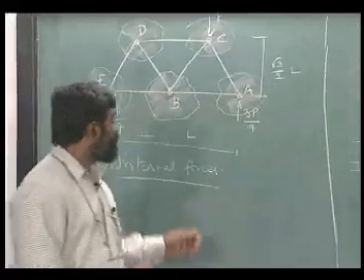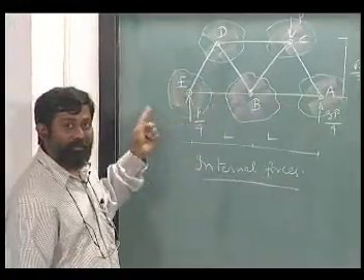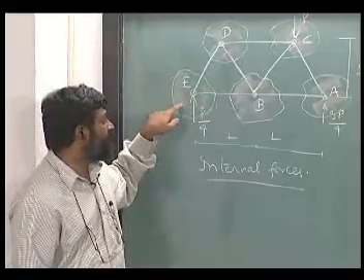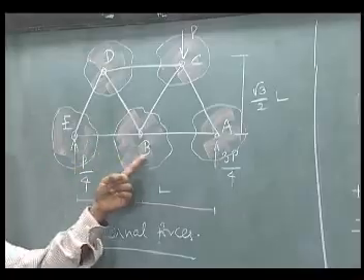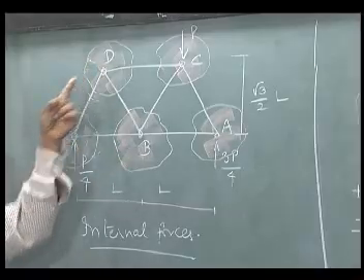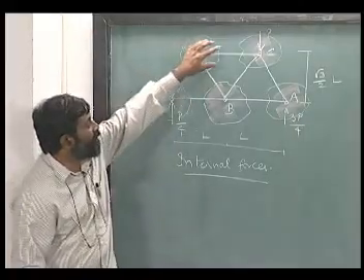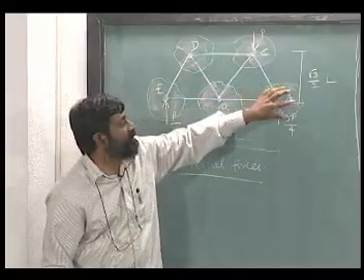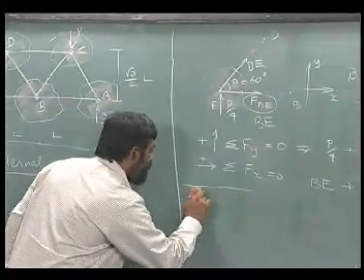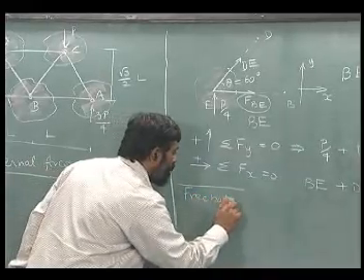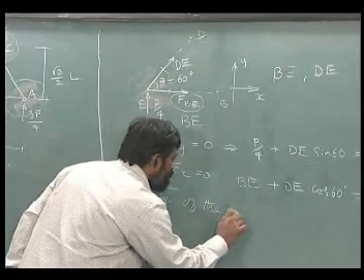Okay. Going back to this, we looked at this free body, and from this free body it was possible to find out the force acting on this particular member BE and the member DE, right. Similarly, I can do it for each one of these free bodies. Okay. So, I have free bodies now of each of the joints.